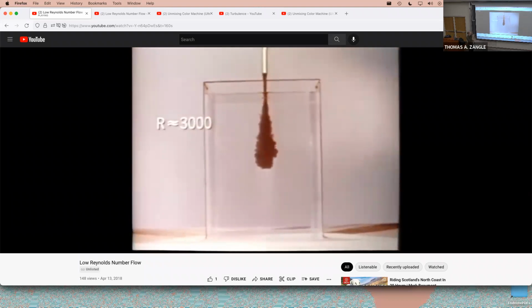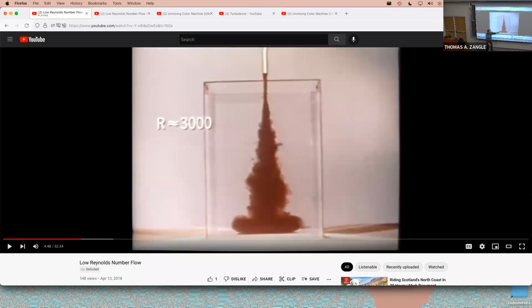This jet becomes turbulent. So now we have turbulence, right? So now we're at a Reynolds number above 2000. And you can see, right, that first of all, just like in that Reynolds number 200 case, the influence of inertia is definitely much larger than that of viscosity, because the jet penetrates deeper into the fluid. But then in this case, the Reynolds number is so high that it also transitions to turbulence.